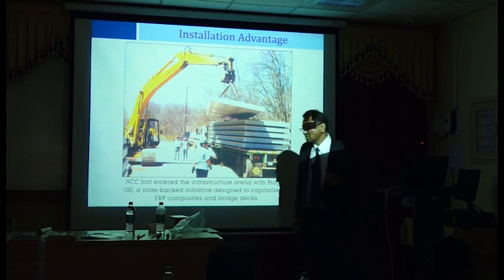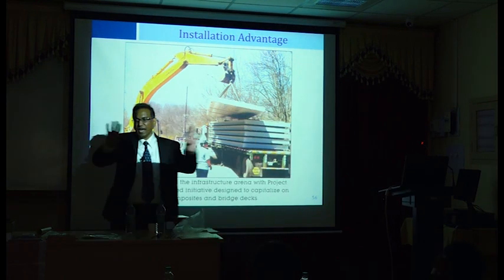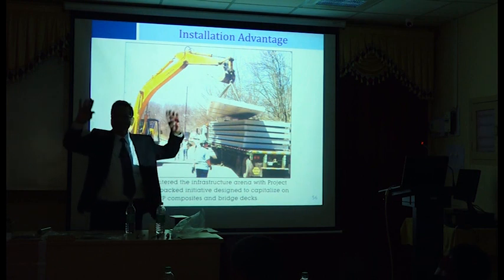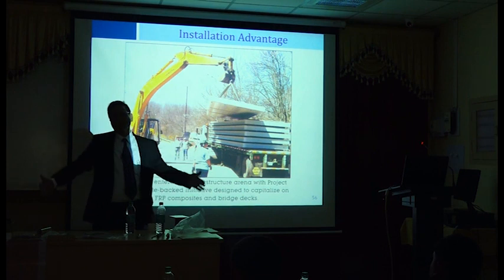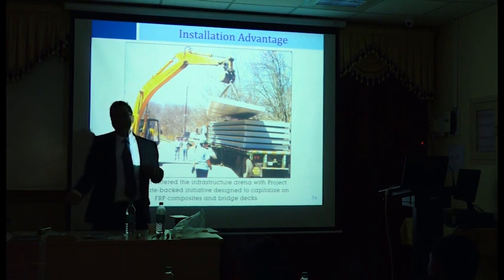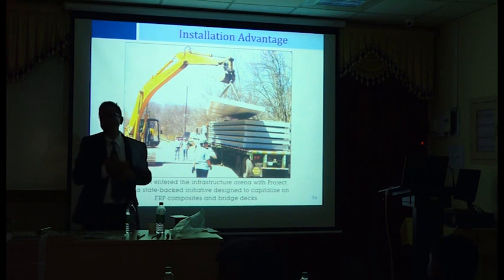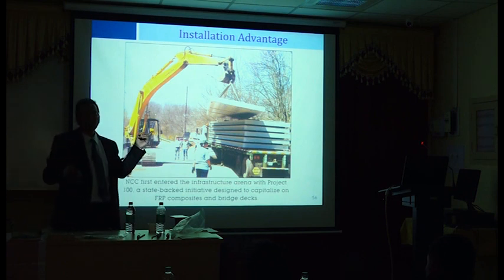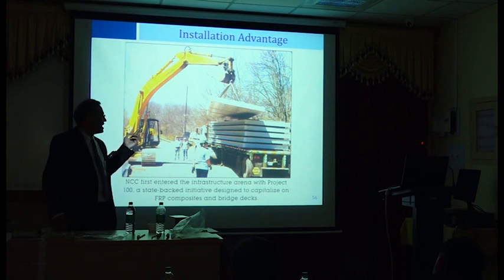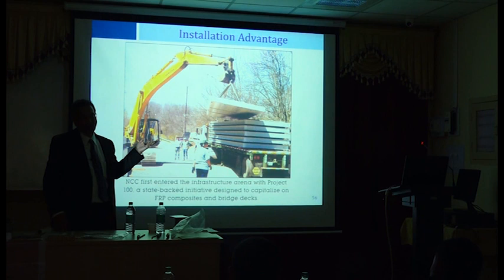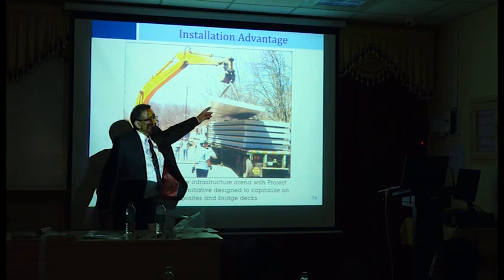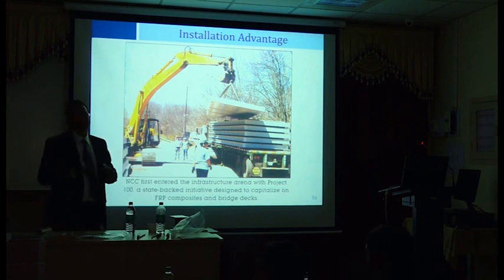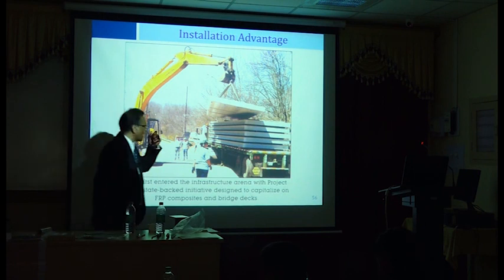Okay. So sometimes weight is such a big deal. I'll tell you why. Let's say you are designing a bridge and you are using a composite or FRP deck. You make it so light, right? So the columns and even the beams, everything becomes lighter because of that. And your foundations, right? That's a big deal too. If your soil is weak and you want to design a bridge on weak soil, instead of going all the way to the rock, if you have to use some kind of piles or something like that, instead of that you can probably get away with spread footing, depending on your design. If you are able to reduce the self-weight of the deck, which is the biggest contributor to weight, that's a big advantage.